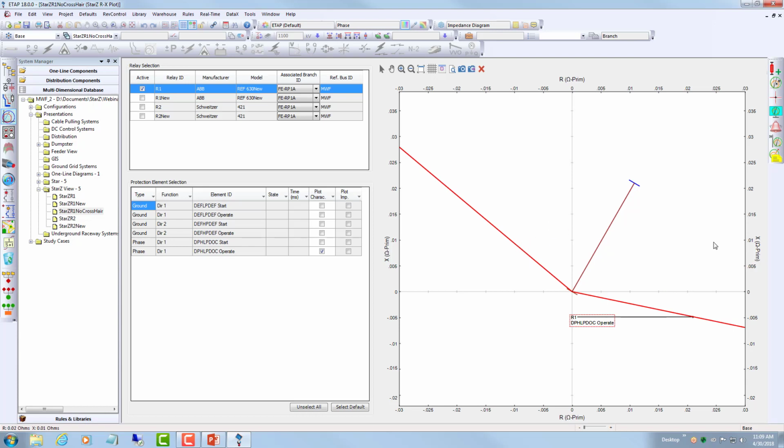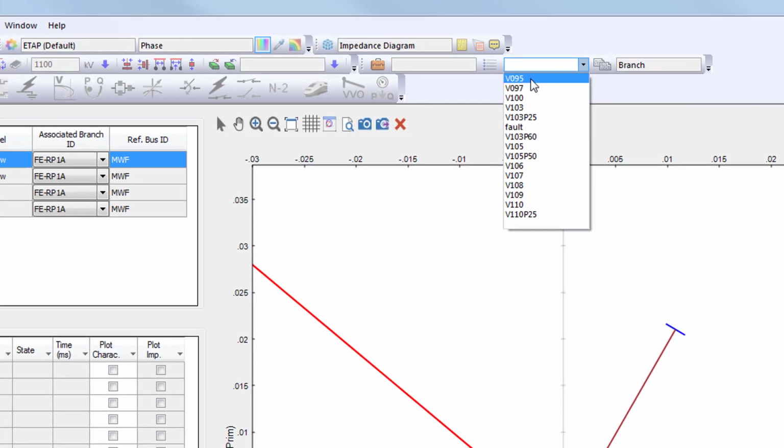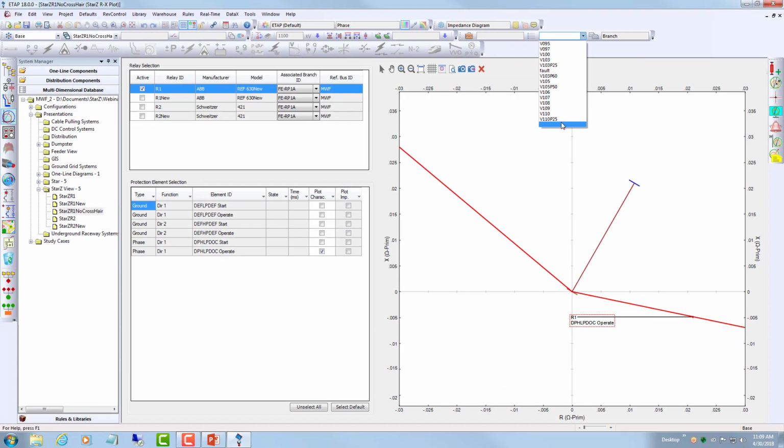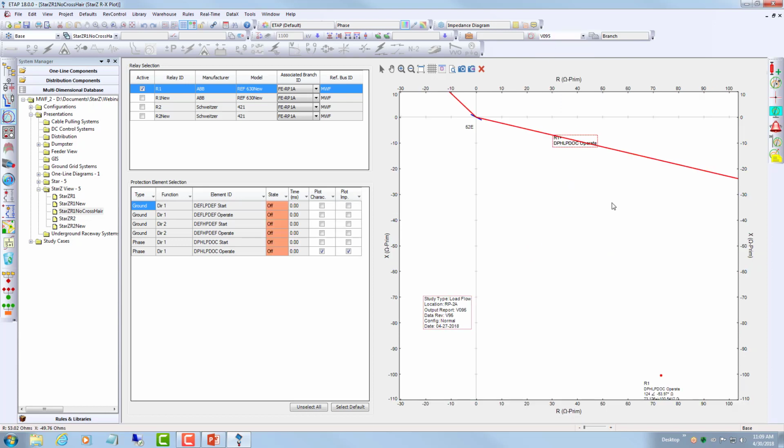Those are the default values, so I didn't touch them, so we can use them for now. Now what I have done is I have been decreasing and increasing the voltage on the utility side. In this case, I'm starting from 95% voltage on the utility side and increasing the voltage to 110% to see what happens. At the beginning, my WTG generation is 0 and my auxiliary power is about 10%. So let's just start with the 95% voltage.